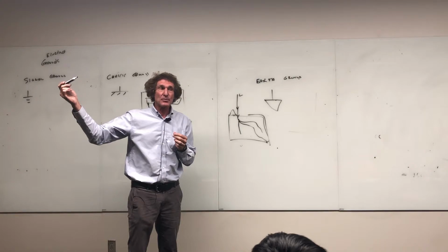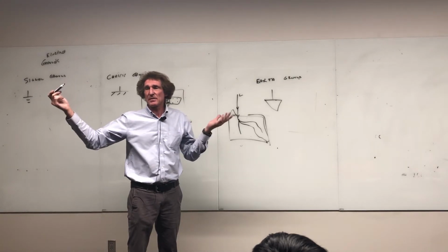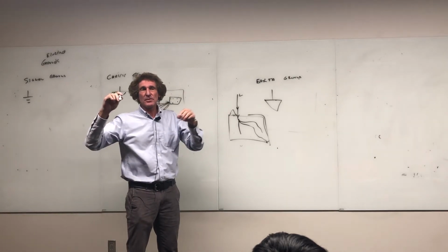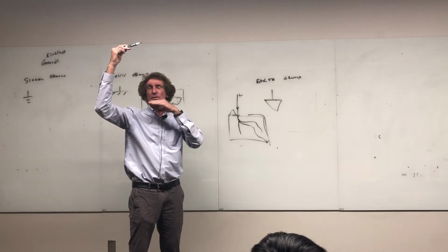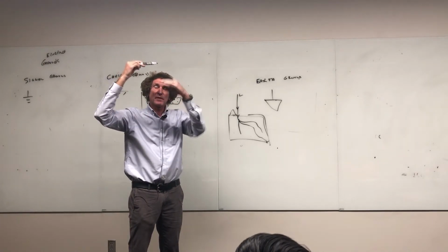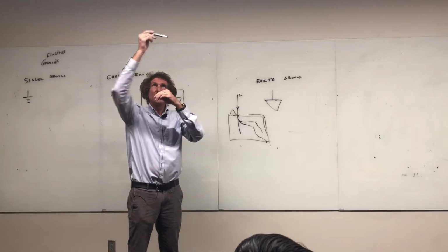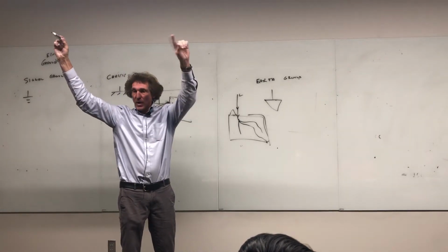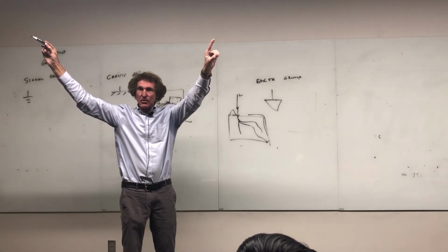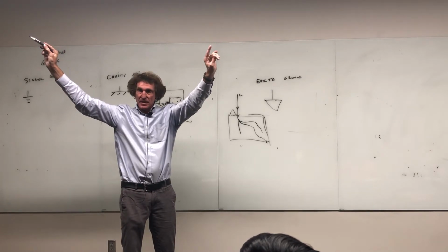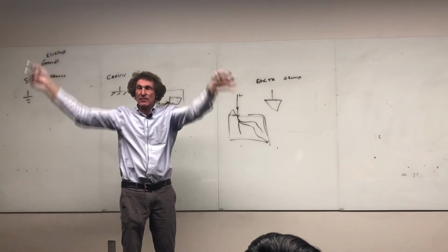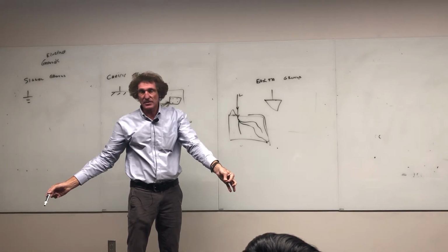And this guy had purchased equipment to make your home safe. The only thing you need to do is, if your house is 50 foot tall, go about 20 foot beyond that, and just hang a thick gauge wire right over the roof. It's called a cone of protection. You've got to make it extend a little, like that, and take it right down to 2 grounding rods. That's all you need, and you're protected.